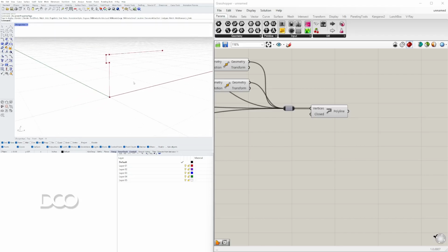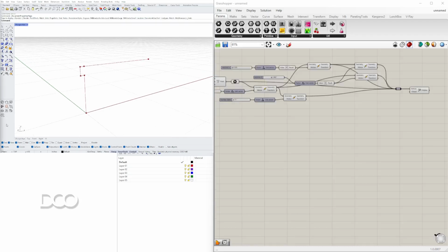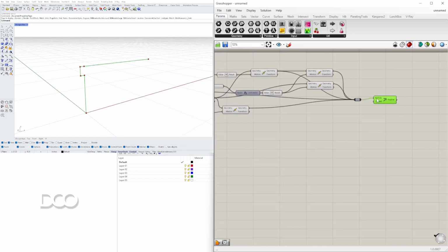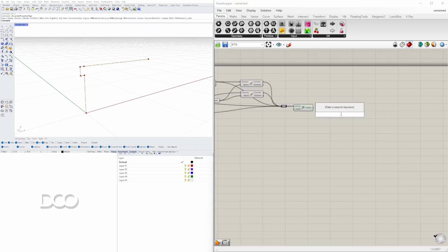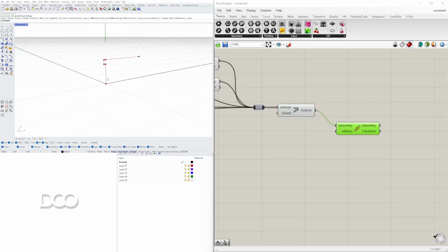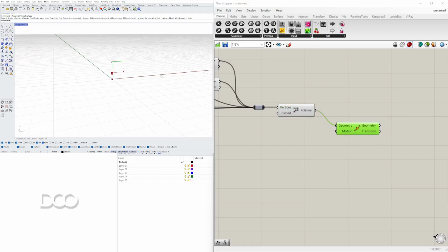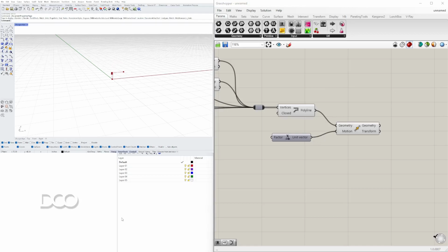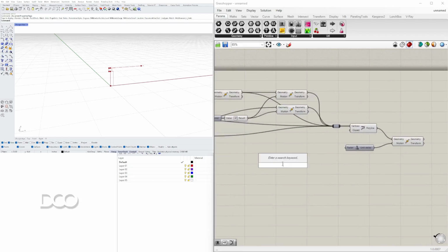Now with this, let's create the continuation of the treads by creating an array and some copies. So here at the beginning, I'll have this polyline. And so we'll go here to move this polyline. In which direction? In the X direction. But as you can see, it only copies one, and we want more than one. So we want a series.